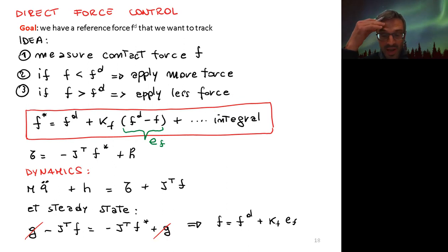On the other hand, we have active methods, in which we design a control law such that the robot can react in a specified way to the contact forces applied by the environment on the end effector. We can measure these forces via a 6-axis force sensor, which you remember is made with strain gauges.